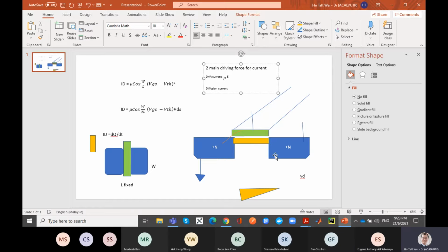You're using the voltage across here to attract electrons, right? So you can argue that the amount of current I can pull depends on my attractive force. How many electrons can I pull up to make this channel participate, and that's dependent on the voltage here as well as the area over which I'm applying that voltage, right? Because this layer of channel is three-dimensional. There's a certain depth here, and there is a certain area on the top here. So if I have a larger width transistor, I can pull up more current, and there's more current for me to pull. And of course, it depends on the material properties, the oxide thickness as well as the mobility.